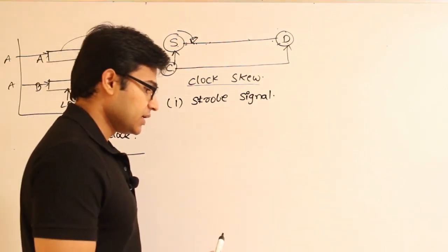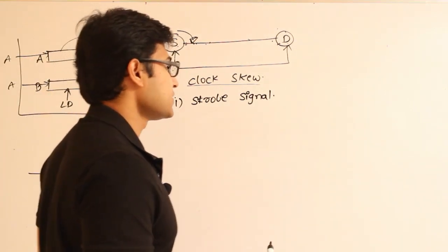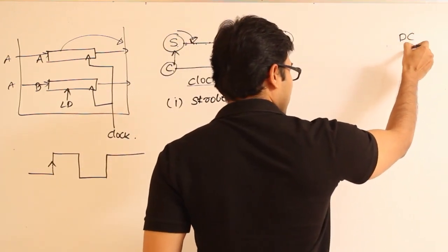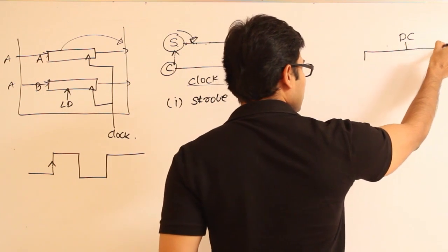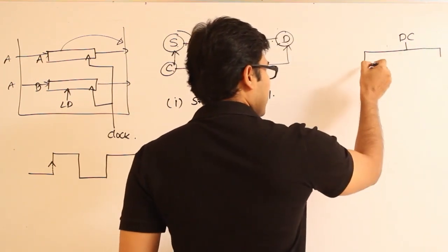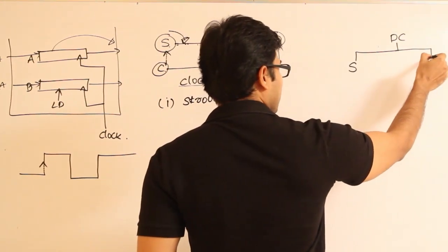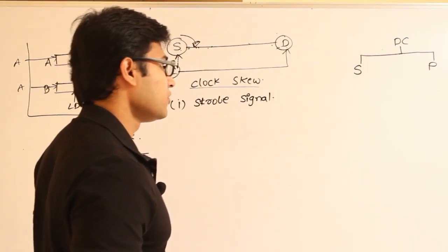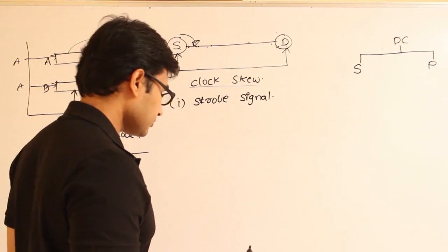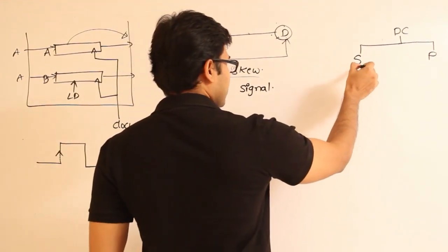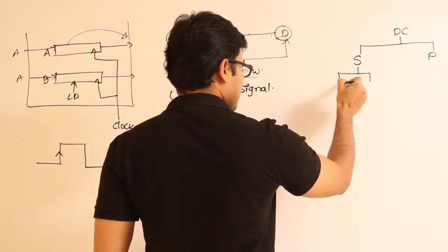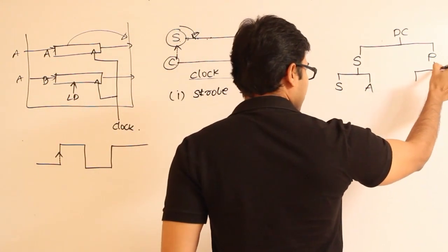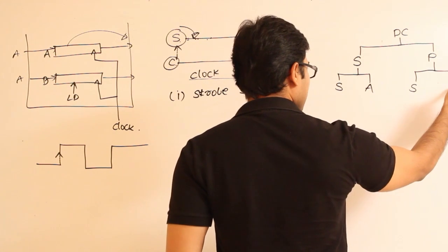If you want an overview of what we are discussing, we are talking about data communication. What are the various modes in which we can communicate data? Either you can go with serial or you can go with parallel, right? That depends on how long a distance you are going to transmit the data. In serial we have two types, synchronous and asynchronous. In parallel also we have two types, synchronous and asynchronous.